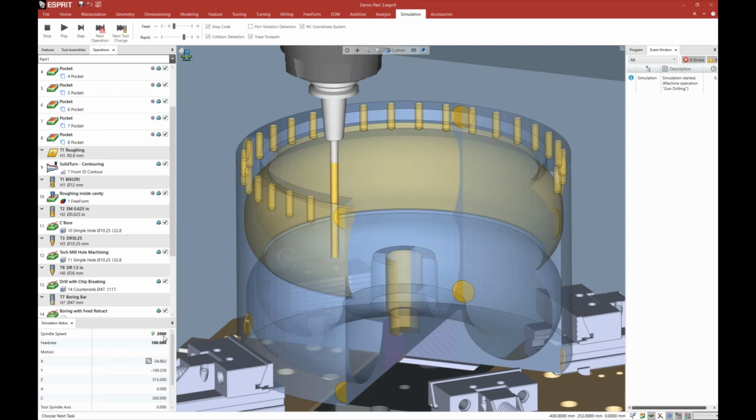One more step. It reduces that feed rate now, kills the coolant, does a dwell, and then it retracts up to 2 millimeters above the hole. So just like how I defined in that operation, you can see that's what it's doing here, and then the posted code will match that as well. So again, those custom drilling cycles are really a great improvement, and that's a really cool tool that I'm pretty impressed with. Really happy about that one.